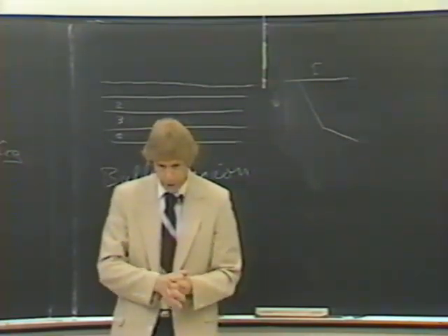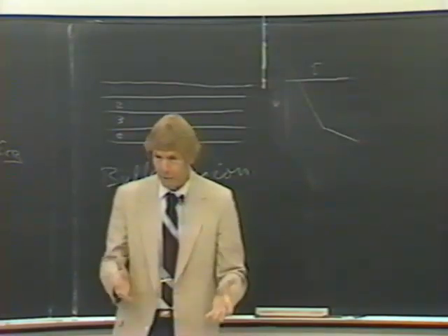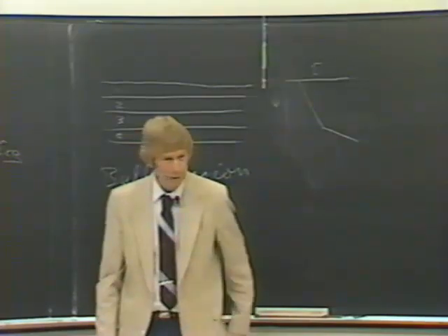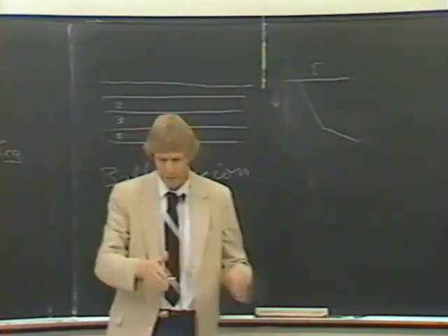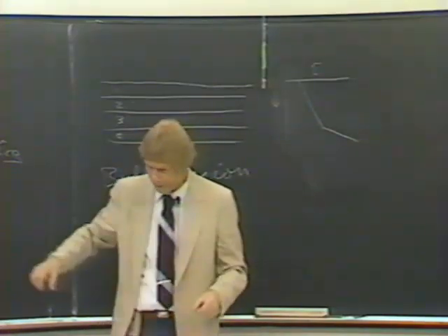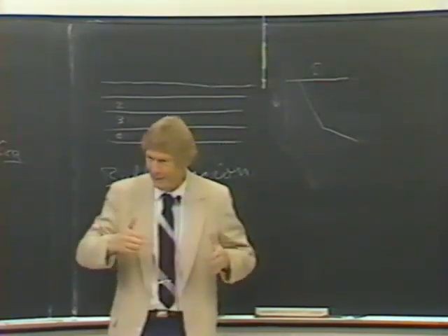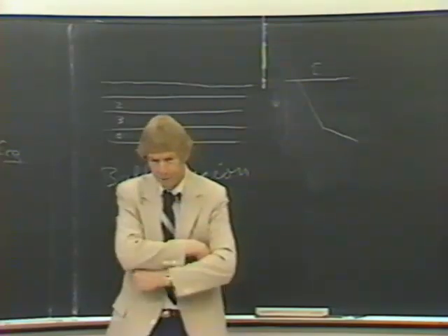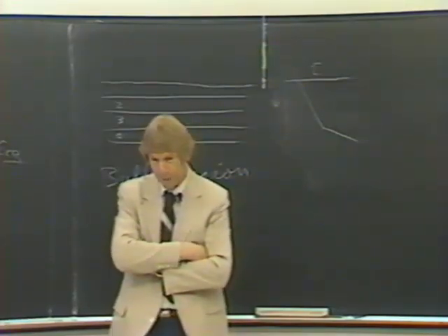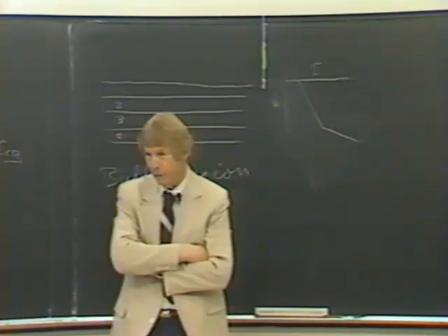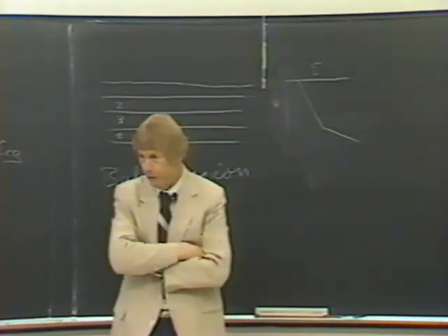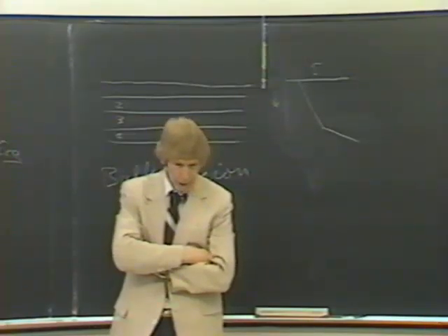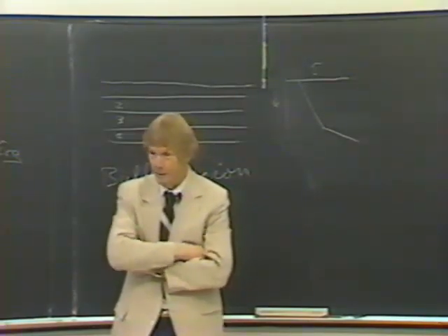And then having this model, we needed some way to verify it. It was a pretty crude model. It was a stream flow model. We essentially divided the flow into vertical slices, and the flow went around the caissons. So we set up a hydraulic lab at Rosario. It's a university lab about 200 kilometers from Buenos Aires, and put in a small caisson model, and